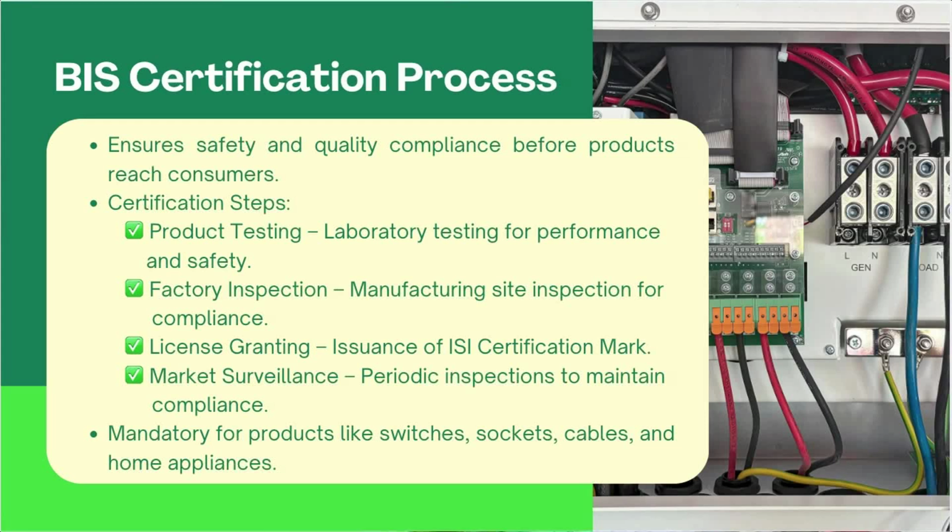Then license granting. So if a product meets all requirements, the BIS grants the ISI or Indian Standards Institute certification mark, which indicates quality approval. Then there is market surveillance. So here the BIS conducts regular inspections and surprise checks to ensure that the certified products continue to meet safety standards. BIS certification is mandatory for several electrical products including switches, sockets, cables and household appliances to ensure user safety and reliability.